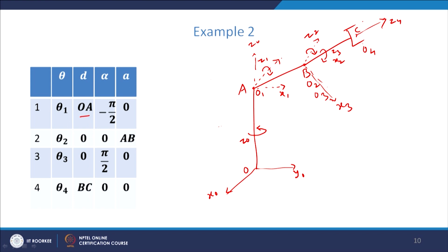And at the end effector, as the convention, we can fix the y direction as the line joining the fingers, and the x direction as y cross z direction, which will give the x4 direction. So, using this, now we can fix the B1, B2, B3, B4 points as the intersection of, for example, B1 is the intersection of Z0 and x1.